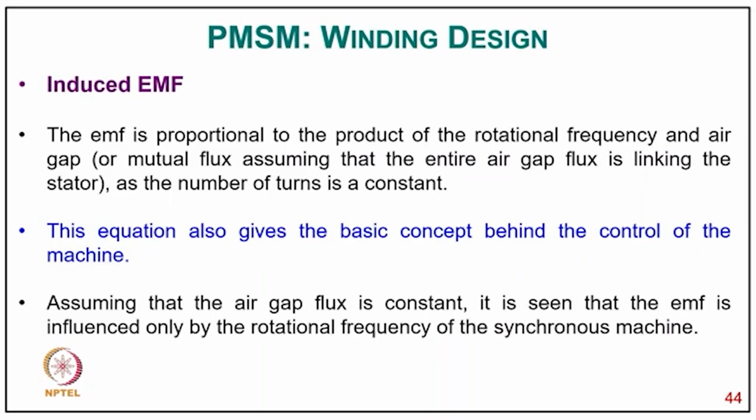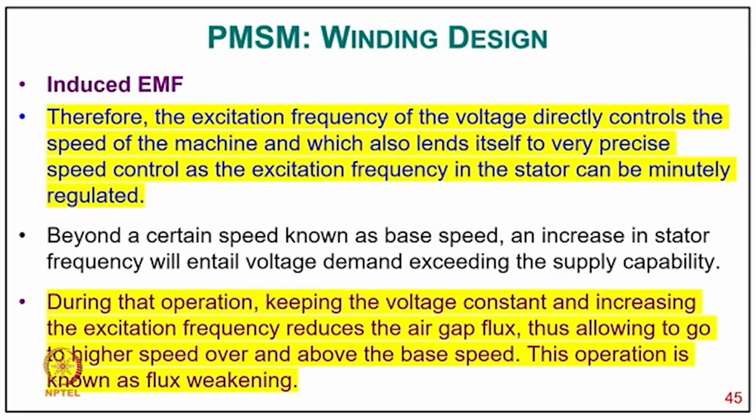This equation also gives the basic concept behind the control of the machine. Assuming that the air gap flux is constant, it is seen that the EMF is influenced only by the rotational frequency of the synchronous machine. Therefore, the excitation frequency of the voltage directly controls the speed of the machine, which also lends itself to very precise speed control, as the excitation frequency in the stator can be manually regulated.